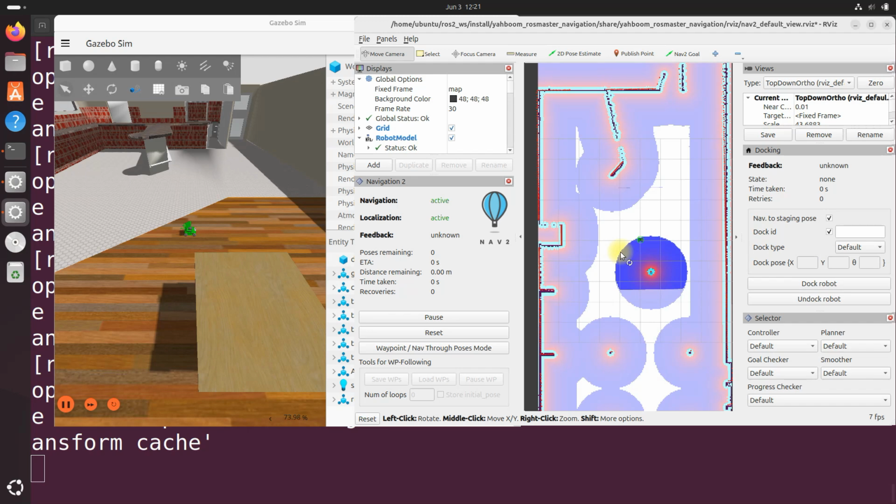For a real robotics project, I recommend the Isaac ROS map localization package by NVIDIA, which will enable you to automatically localize the robot based on a PNG version of the map. That's a very cool thing you can do in a real robotics project. So you can either do it using a package like Isaac ROS map localization, or you can set it manually like I did by publishing the initial pose.